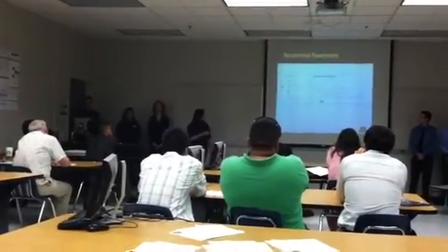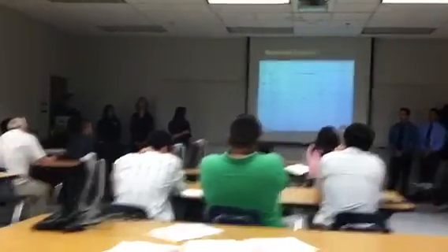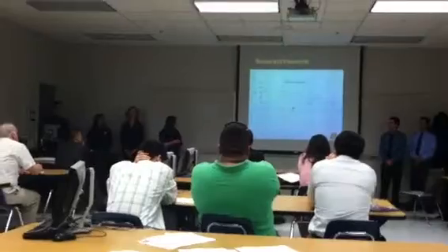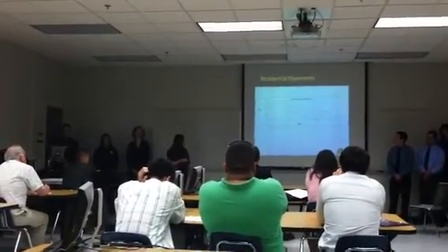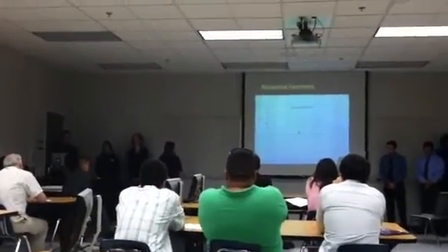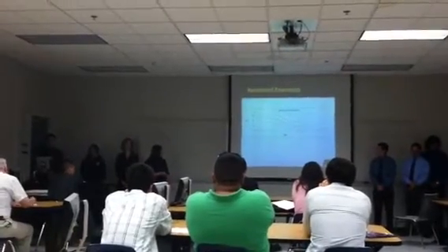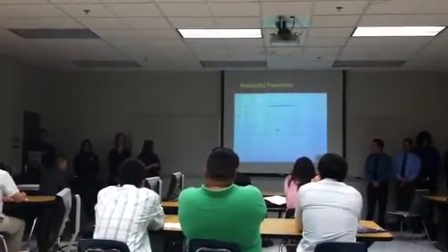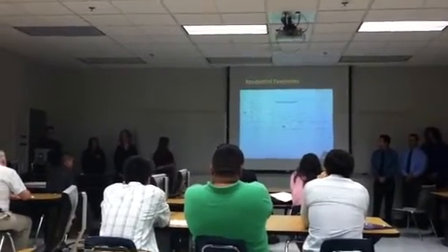This represents the residential roads we investigated. From looking at the graph, we can estimate that most of the roads need to be repaired between 25 and 30 years. We can also conclude that residential roads, compared to arterials and collectors, have the worst pavement conditions, since our points right here are below the 55 number.